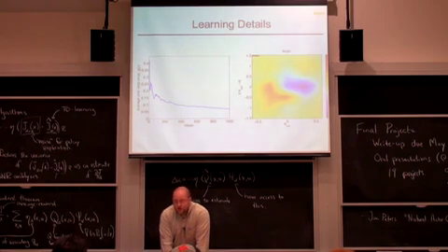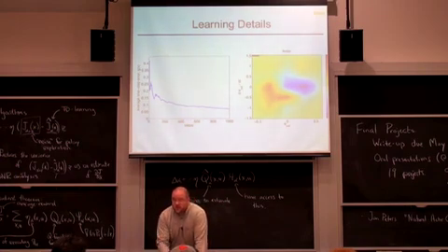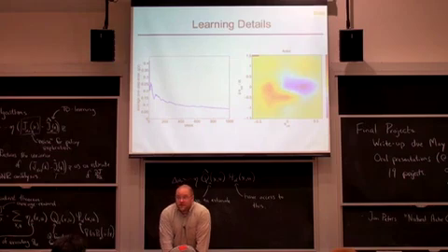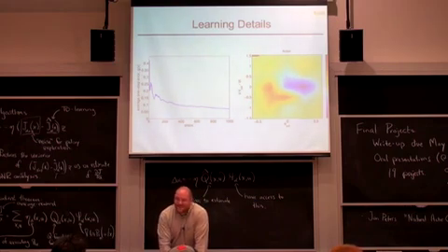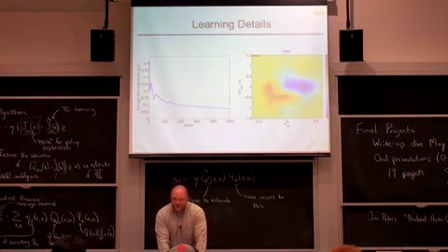Energetically, the mechanical cost of transport, if you just look at the actual work done by the actuators, was comparable to a human, 20 times better than Asimo. But if you plot the current coming out of the batteries, it was like 3 times worse than Asimo, because it's got these itty bitty steps and a really big computer, and that was, in retrospect, maybe not the best decision. Although I never had to worry about computation. I never had to optimize my algorithms to run on a small embedded chip.